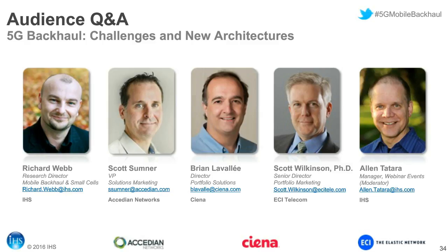Yes, some of the things can scale, like PON, for example. My concern was more down to the actual physical media, where I believe that fiber, if you can get it out there, if you have to run something, you might as well run fiber and not copper. If somebody wants to run copper, it's probably because it's already there. It might be in the building for an indoor 5G cell, for example. And on the millimeter wave, there is talk about having a 5G radio that will operate in that frequency range. Actually, there's a lot of discussion about what ranges 5G will need and will actually use. The millimeter backhaul I was talking about are the products that are available today that will not scale to the tens of gigabits per second that you'll need for a 5G-enabled macro site.